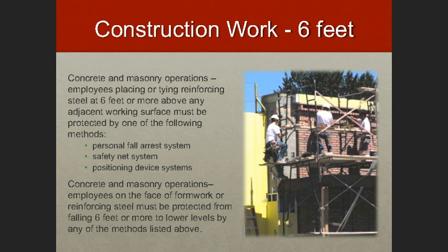And so please remember that construction is defined as construction, alteration, and/or repair, including painting and decoration. So if you're painting, or doing some decoration like hanging up some photos or artwork, that technically is construction work, and we have a 6-foot height requirement.